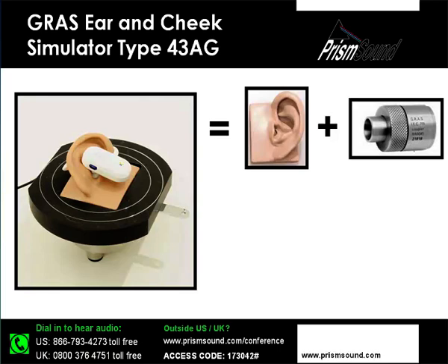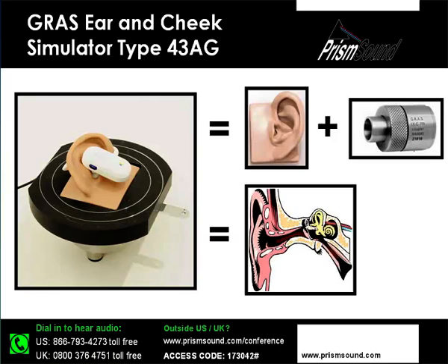Inside the fixture here we also have what we call an IEC 711 coupler, and this is designed to closely emulate the acoustic impedance of the ear canal, the inner ear. So in other words, this complete test fixture is designed to give us a close working model of a real human ear, and this means that we can make repeatable measurements without needing to have a human subject to subject to our acoustic measurements. And that's both impractical in terms of the man hours involved in your human subject, and it's also potentially dangerous if you're talking about inserting probe microphones into a human ear.